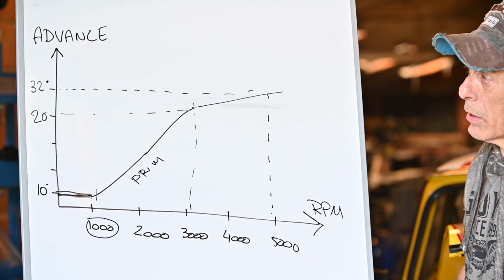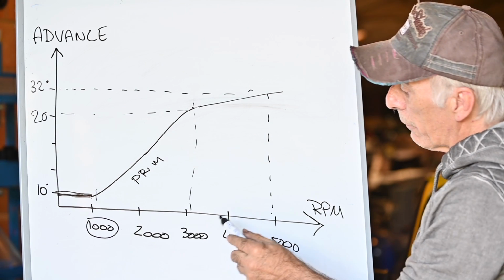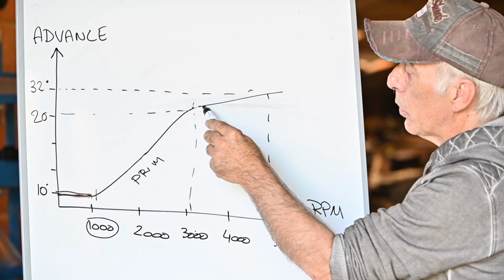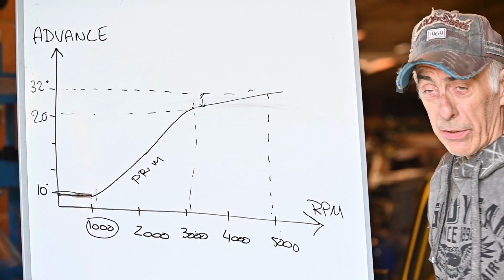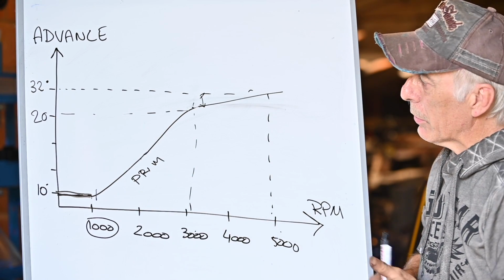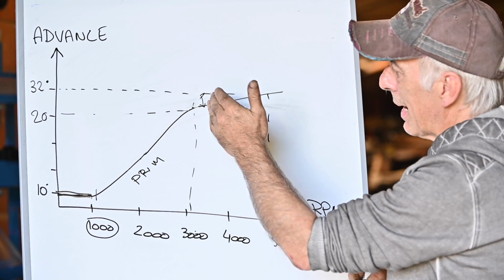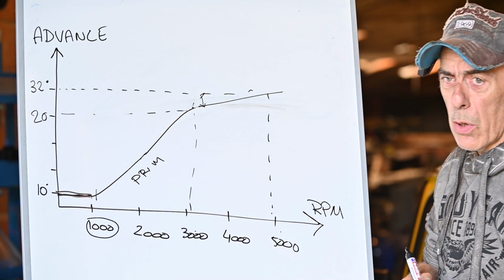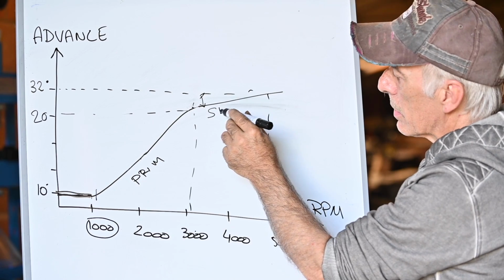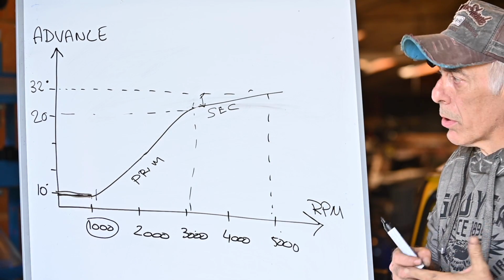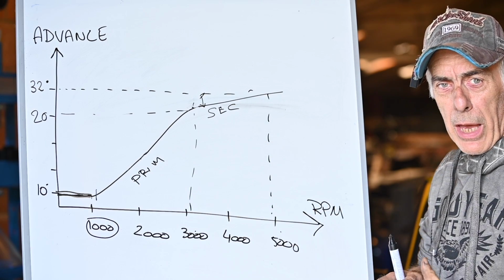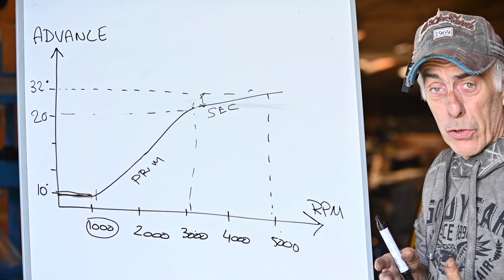So that's about 10 degrees increase or more. And then from 3000 to 5000 RPM, we don't want to have such a huge increase anymore in terms of advance. I know my figures don't match up too much, but that's what we want to have at that moment in time. We want to have less acceleration or advance actually of the bob weights, and that's why the secondary spring now is coming in, and that is stronger, so the bob weights will have less effect on that. So that's the mechanism that you apply with bob weights with centrifugal force.